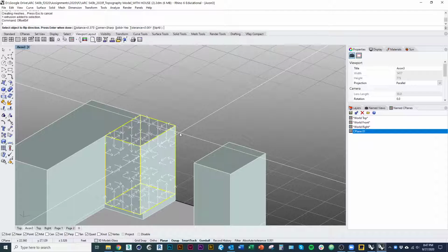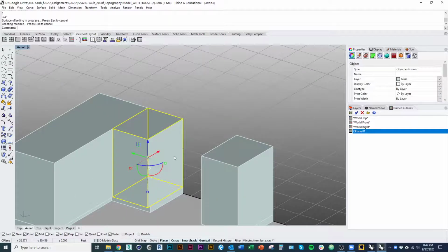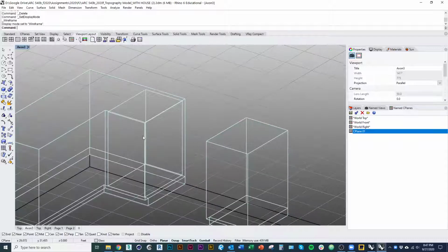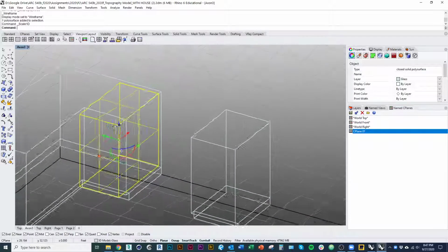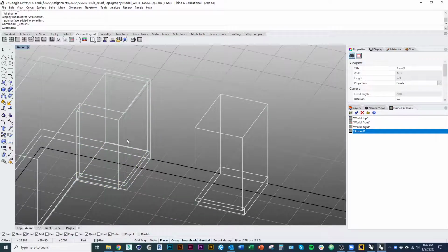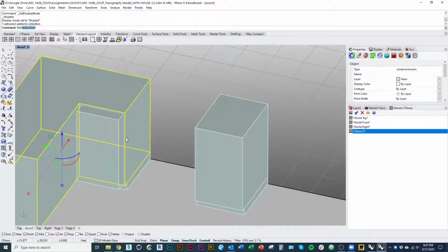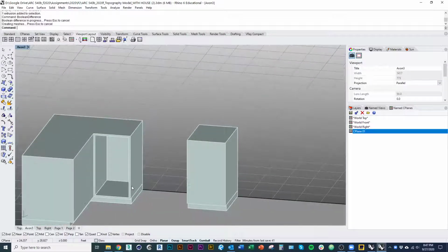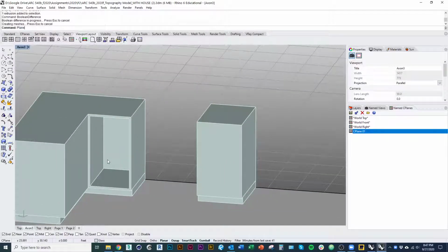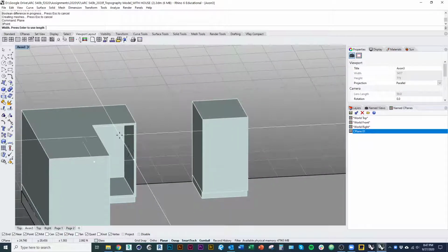Imagine we're using 3/4 inch plywood. There it is. I'm going to scale it to come out of the front there. And I'm going to do Boolean difference. That's how to model it kind of as one element. We could certainly do a plane in here if we wanted to model the shelving.